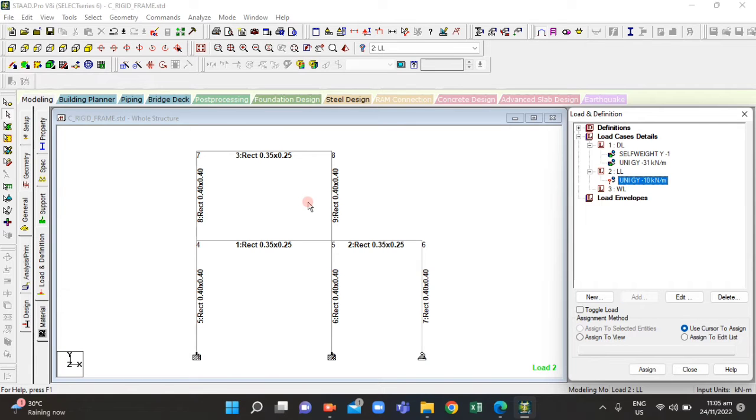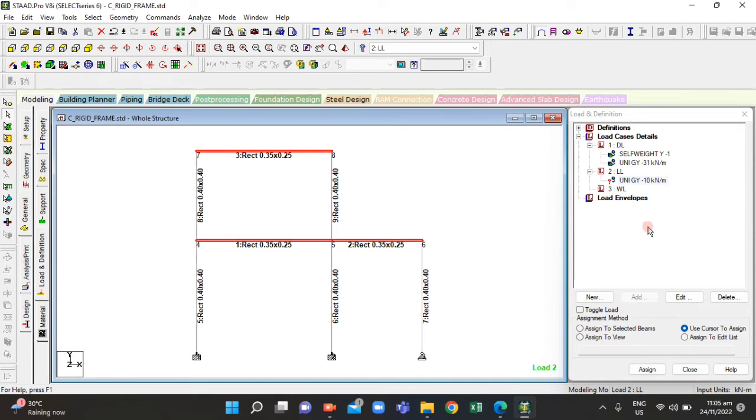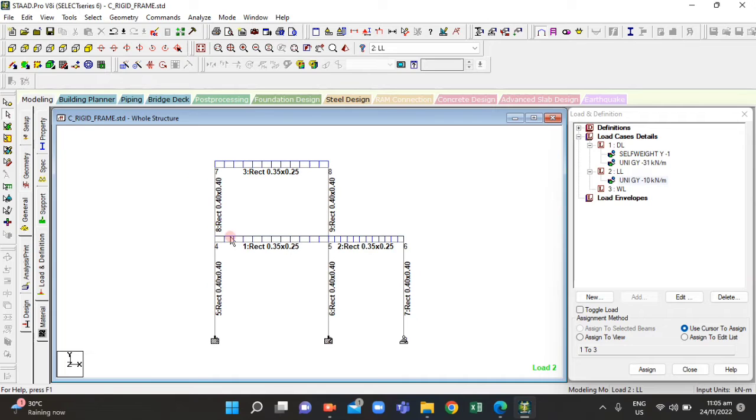Then just gonna highlight the beams, highlight, and there. After that, now we're going to apply the wind load. What we had done a while ago is actually the application of the wind load, 40 kilonewton from the topmost portion of the structure, and from the topmost portion of the structure, that's 4 meters going down or lower, that's actually the 20 kilonewton wind load applied.